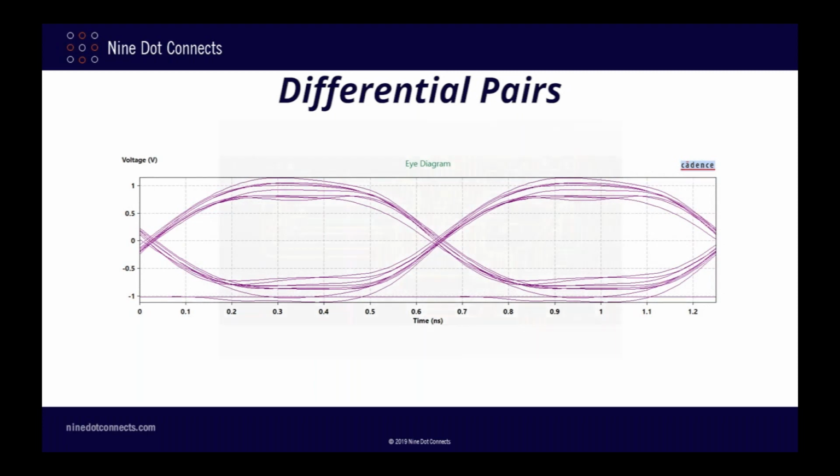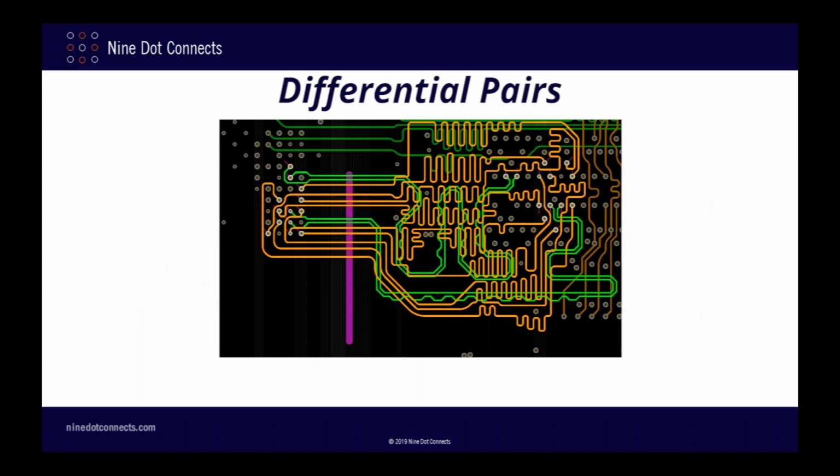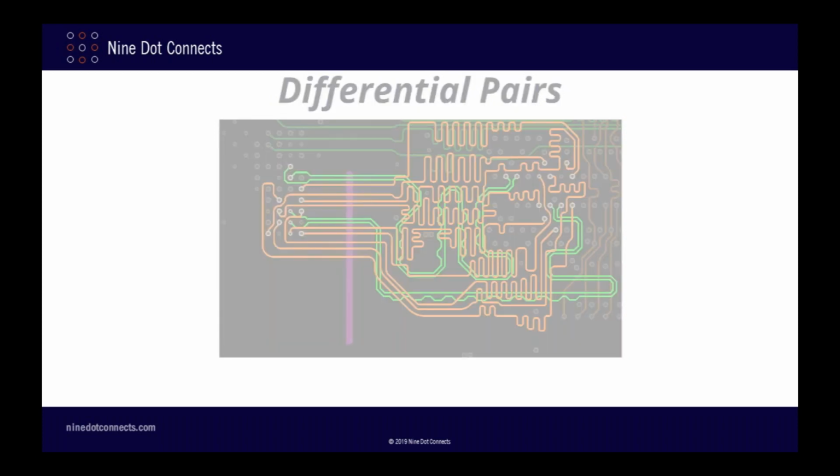I'll give my usual caveat here that I'm just showing a high-level analysis of this effect, so be aware that there are other aspects that you might need to deal with, such as the impedance mismatch of the gap section. But for the most part, you can balance things out and end up with a remarkably robust signal should your layout require crossing split planes. In fact, I think one of your biggest problems will probably be just convincing your colleague that it is okay to route things this way.